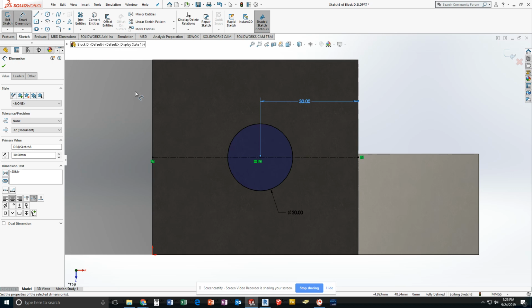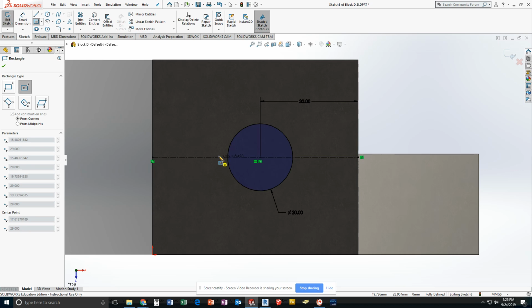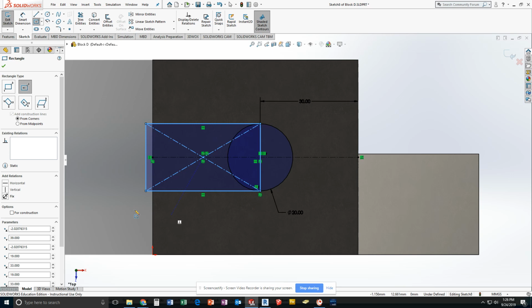The next tool that I'm going to use is brand new. Under Corner Rectangle in the menu here is an option called Center Rectangle. What this does is it lets us draw a rectangle very similar to the way we draw a circle. I can pick a first point as the center of the rectangle, and then I draw out to define another position. I'm going to make sure I try to get on either the 6 o'clock or 12 o'clock position of my circle. Well, I know mine's hanging off right now. I'll size that up again later.